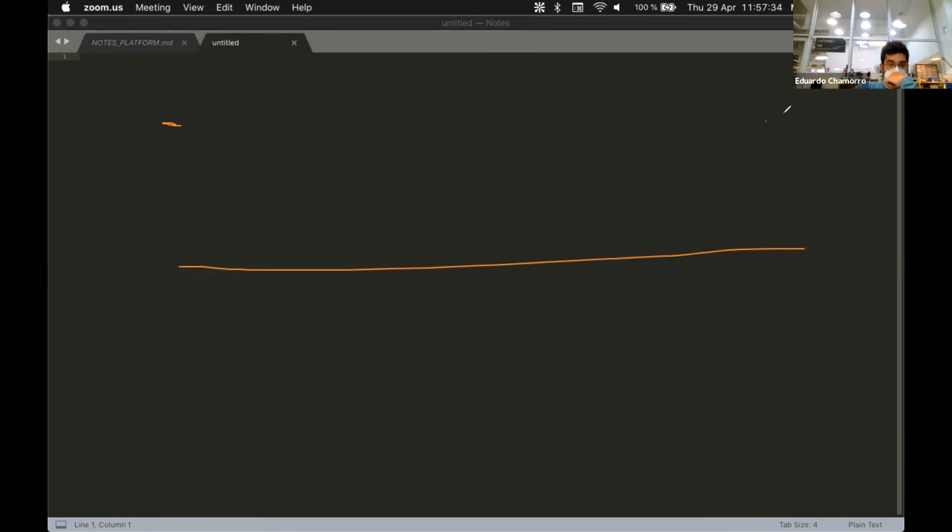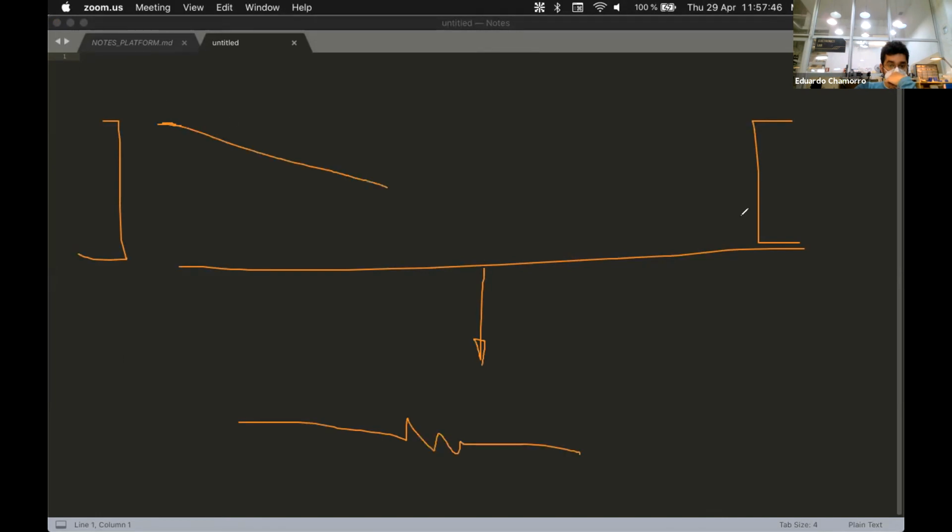Imagine that your sensor is on this end and what you're reading is here. Since the cable is equivalent to a resistor, at some point there's going to be some voltage drop. If this is too long, since the resistance is in ohms per meter of cable, you want to reduce the ohms per meter, but if you have very long cables, that is going to be an effect.